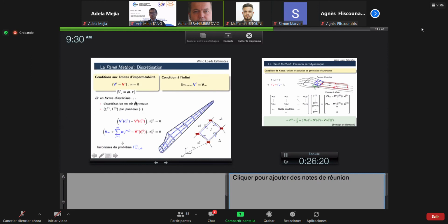So this solid velocity can be computed by the steady rotation of the blade, the rotation being expressed by omega, and r is the radius from the point around which it is rotating. And then you set this equation, you express your velocity interaction in terms of this strength of the vortex. Plus you add, by superposition, the velocity before you enter the farm.